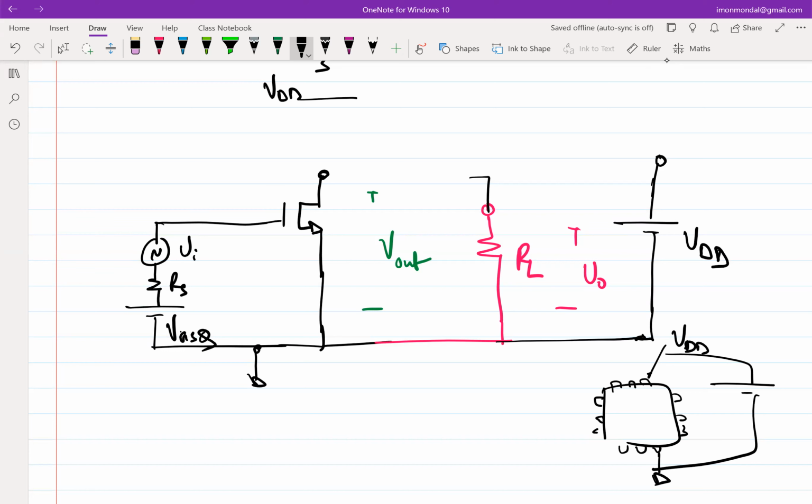Oh, where do you get current source requirements here? It's not very obvious, right? Why should you have a current source? Another resistance where? Drain to VDD. Okay, yeah. I can have an explicit resistance, that I can definitely have. So let's put one more resistance here, between drain and VDD. This doesn't violate any condition, because RD can be an explicit resistance that I put in my design. When I put an explicit resistance, I have access to both terminals. So that can be done. Okay, so I put another resistance RD, fine.